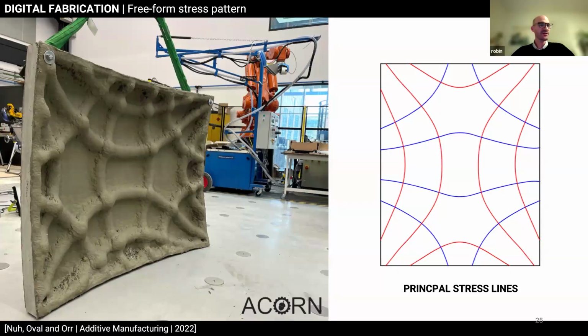If I connect the two projects that we saw, so spraying these concrete elements and trying to get these rib floors that we saw before. Digital fabrication allowed us to produce these pieces with these ribs, where you could imagine that they start carrying higher forces than the rest of the shell. You can maybe have post-tensioning running through. That was thanks to the rheology of the material.